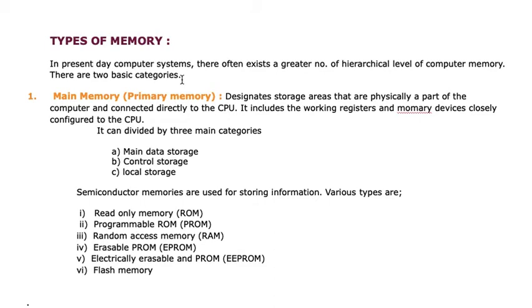When selecting a memory chip for use in a digital computer, a designer normally has a wide selection from which to choose. Some features that are commonly examined during selection of a specific memory chip are capacity and organization, timing characteristics, power consumption, bus loading, physical dimensions and packaging, cost, reliability, and availability.